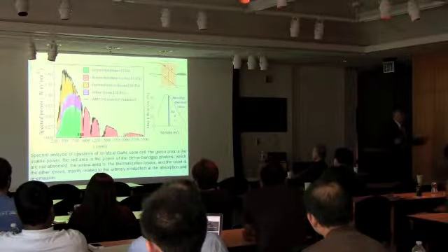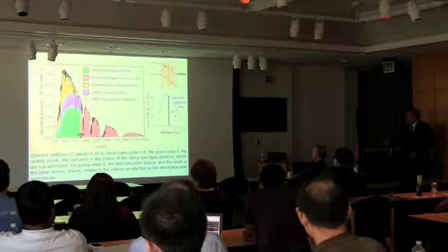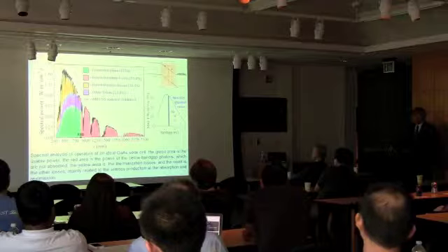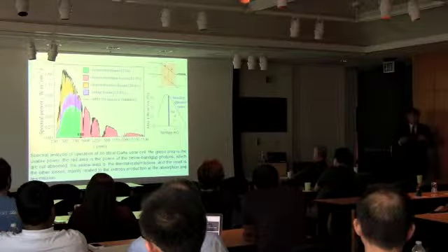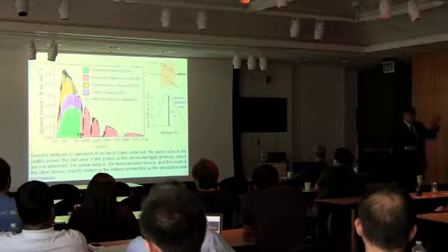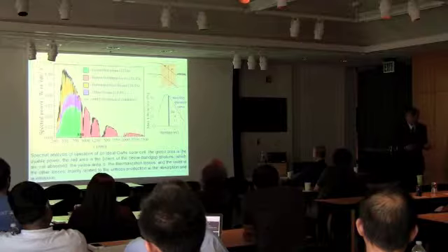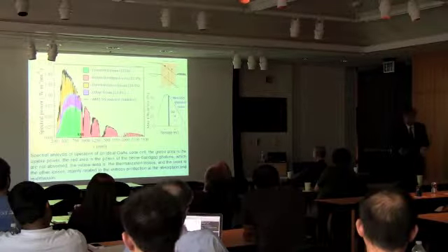It will always be smaller. If I go to a zero band gap material, then it absorbs absolutely everything. But it will have completely zero efficiency, because the voltage that I can take from this solar cell will be zero.